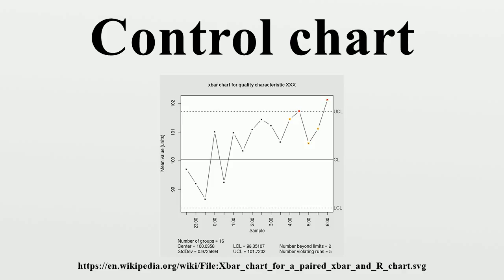Action on special causes. 1. Any point outside of the control limits. 2. A run of 7 points all above or all below the central line. Stop the production, then quarantine and 100% check, then adjust process, then check 5 consecutive samples, then continue the process. 3. A run of 7 points up or down. Instruction as above. Chart usage if the process is in control.